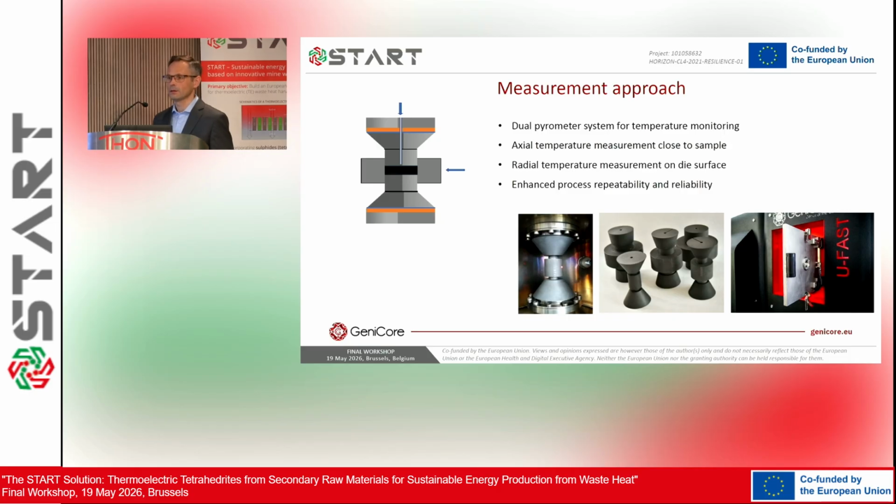Typically, sintering processes are conducted in graphite dies. During the process, temperature can be measured in different ways: through the hole in the pressing stamp by a pyrometer, which gives us information about almost the real temperature of the sample, because the distance between the sample and the point where the temperature is measured is a few millimeters, or on the bottom part of the graphite die.